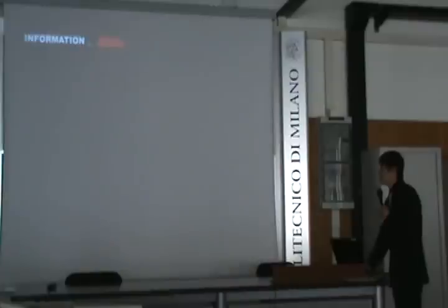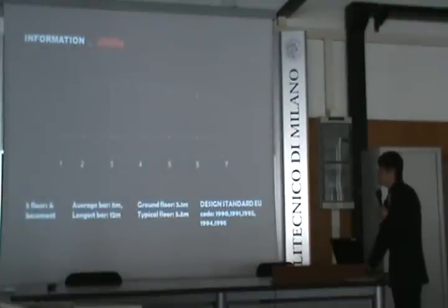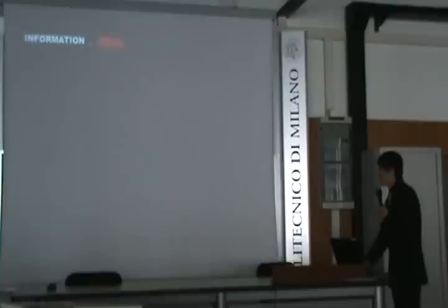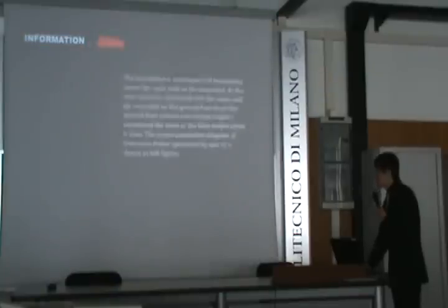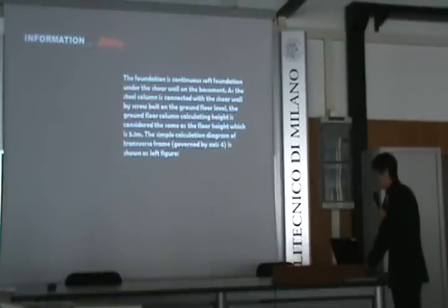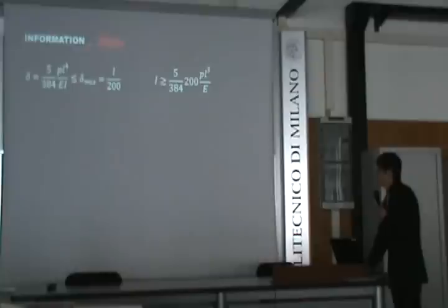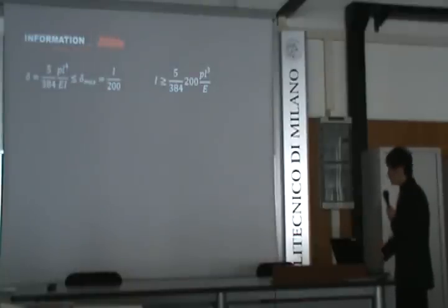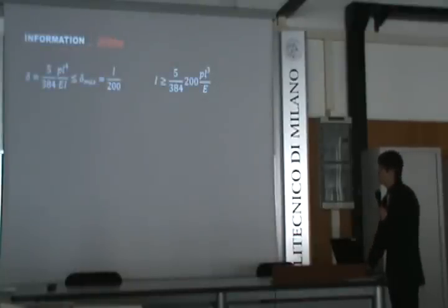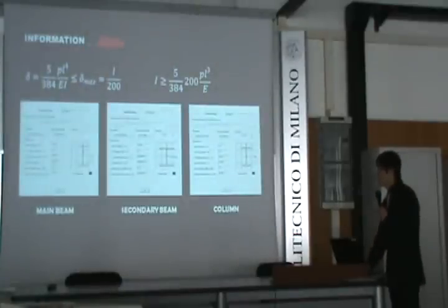According to this basic information, I find the same dimension between each unit of guest room space. So I will choose the simple transverse frame for calculation. It is shown as on the left figure. After these formulas, I will define the steel profile sections of the beam and column.